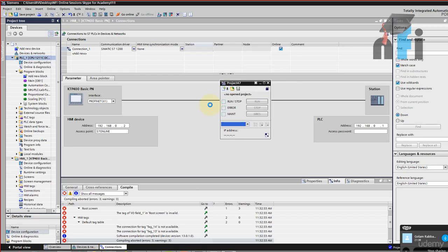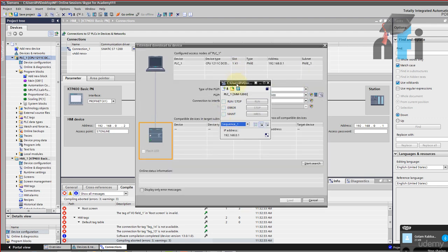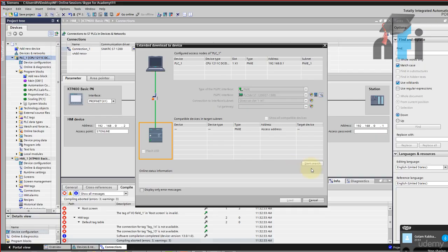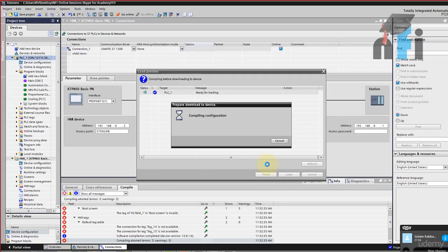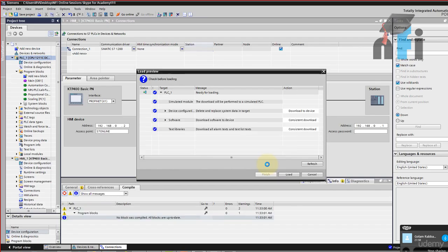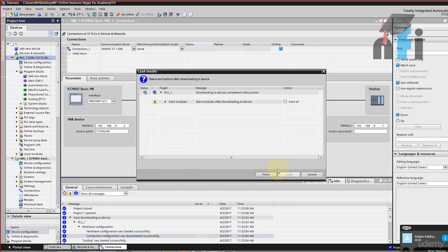This is a very crucial part when you are linking your PLC with the HMI. Once you have a good connection, then things become easy. This is the most common troubleshooting part which occurs in the industries as well, when you are going to link your HMI with your PLC. So right now I'm going to simulate my PLC and see if it is being detected by the HMI.